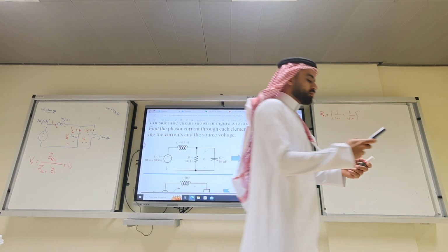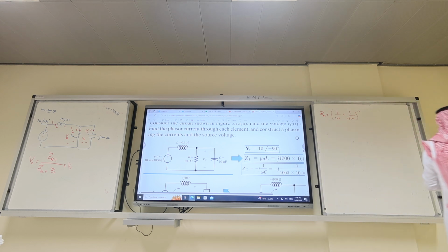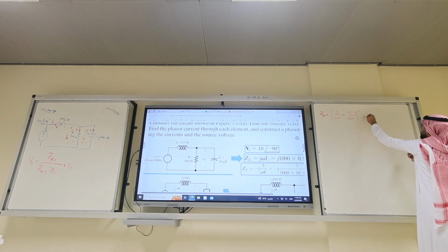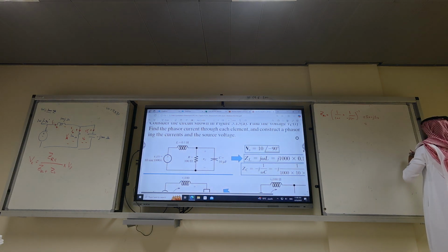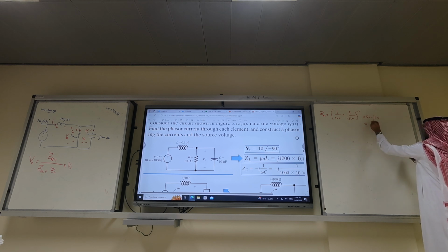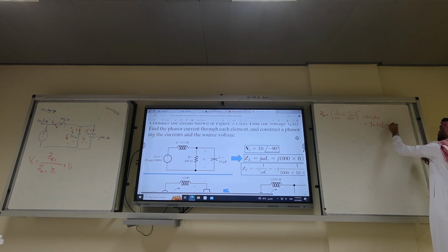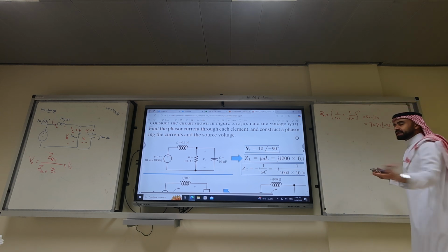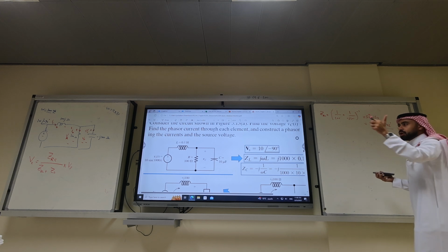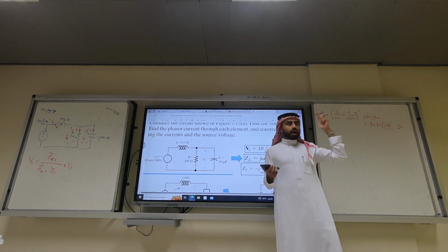50 minus 50. Well, let's use phasors. So it's 50 minus 50J, which is equivalent to 70.71 angle minus 45 degrees. What's the unit? Ohm. So now I can calculate VC directly, because I know Z sub L, I know Z